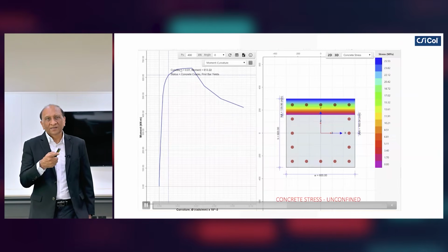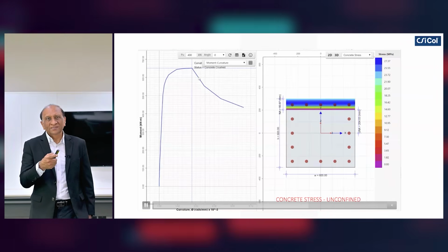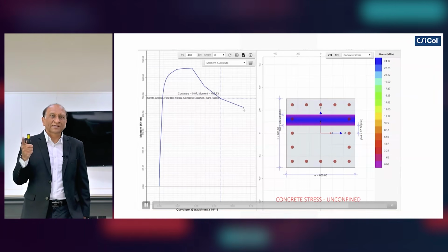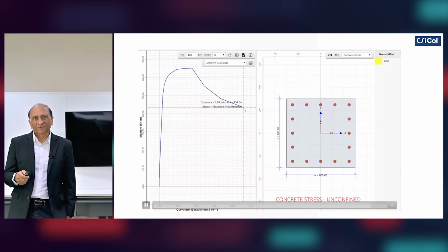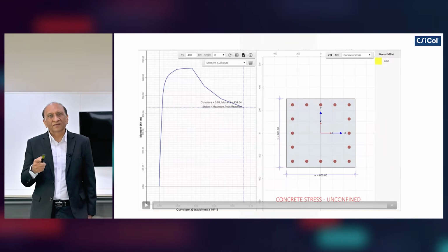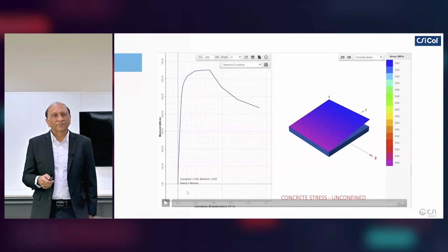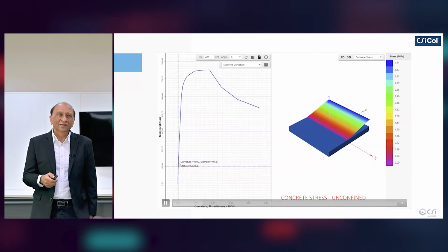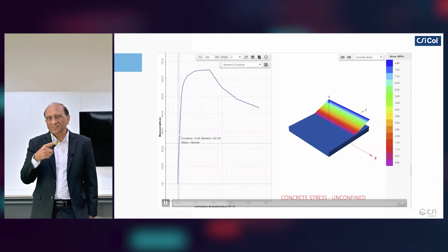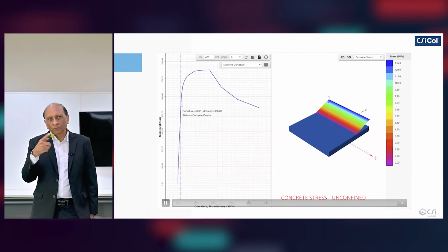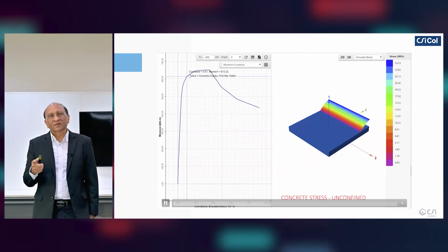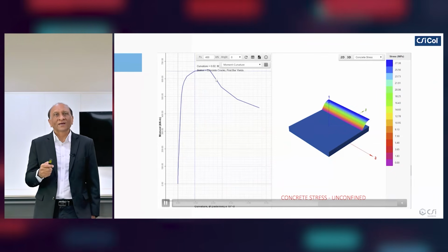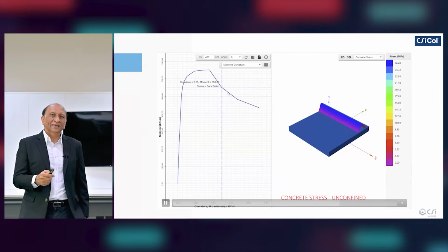You can see from there, and when you move that, you can see that now the concrete is gone on the top, and the concrete section is just only steel is left. So all of that behavior can now easily be determined from the moment curvature curve. There are so many graphs that you can plot, and so many insights that you can get. So using CSI Col or programs like that, you can actually determine the stress strain of the cross section at any moment and any axial load in any direction.